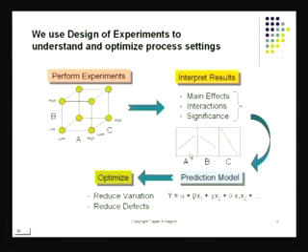Out of these factors A, B and C, you can clearly see that C has the largest effect, the strongest effect. If my goal was to maximize response, I would set A at high level, B at low level and C at low level. If I pick this setting for A, this setting for B and this setting for C, the combined effect hopefully is going to be the maximum value for the response. That's like an empirical optimization. That manipulation has been taking place empirically.